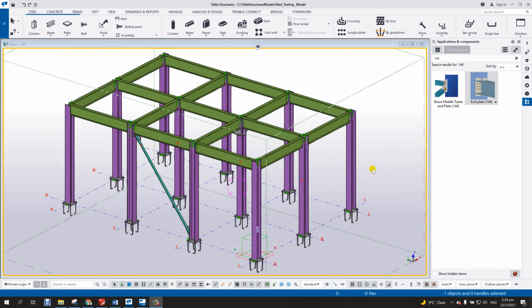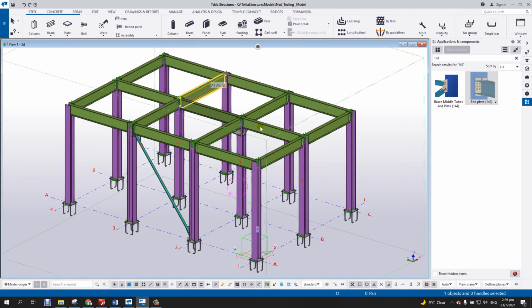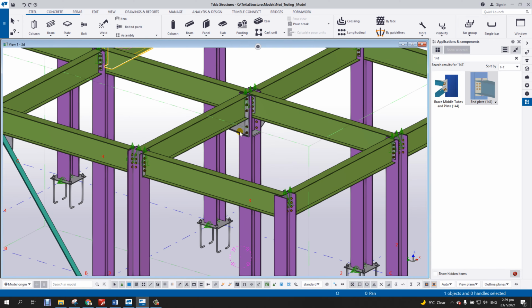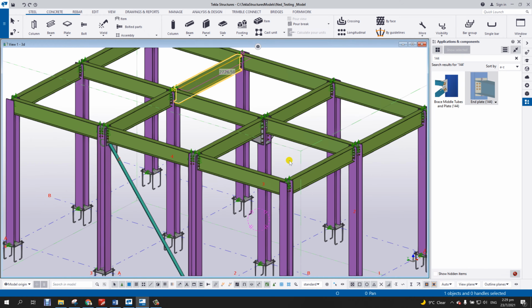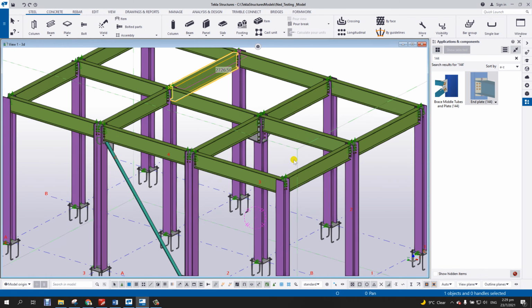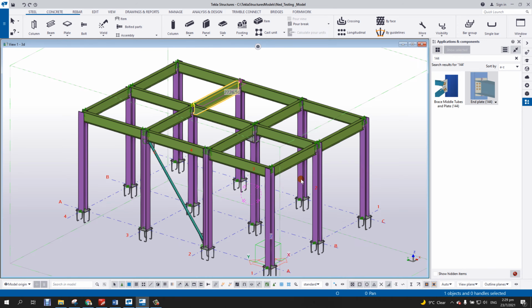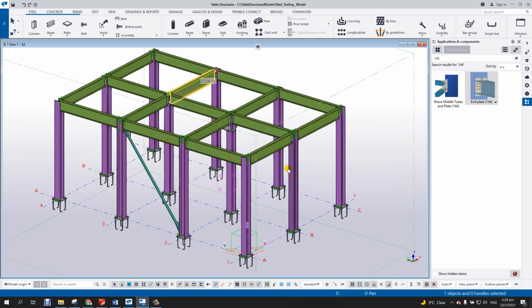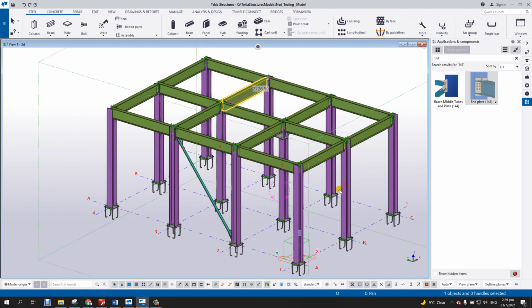The other one is assembly drawing for the shop drawing for the individual assembly, and the single part drawing for the workshop drawing of the plates and all the welded parts to the assembly. And the last drawing is the multi drawing, where we can gather all the single parts in one drawing sheet, or gather all the assemblies in one drawing sheet of paper.